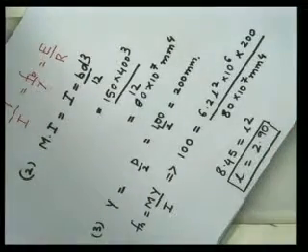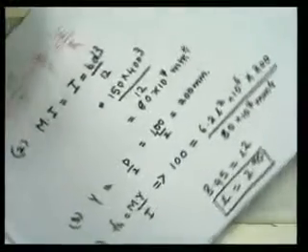Important is, whenever we are given any particular problem, we first have to see what is given. If the beam is given, you can find the maximum bending moment from the loading of the beam. If they have given you a section, then from the section we can find out the moment of inertia, area, and y bar. Then we have to use our equation, that is M by I. It's a very simple problem, right?